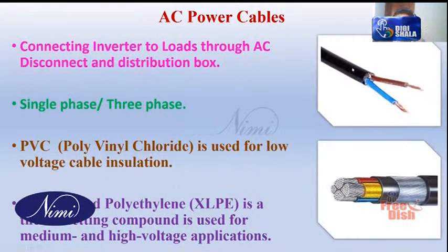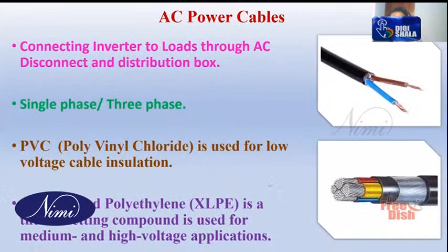Okay. So normally for small voltage systems, we are using PVC as the insulation. So insulation plays a major role. It not only protects, it is also reducing the leakage current. So we should be able to judiciously select the type of insulation. For normal low voltage systems, we are using polyvinyl chloride, PVC. Whereas for high voltage, bigger plant AC cables, we are using cross-linked polyethylene, XLPE. This is having better electrical characteristics. Okay, so XLPE, cross-linked polyethylene is used.